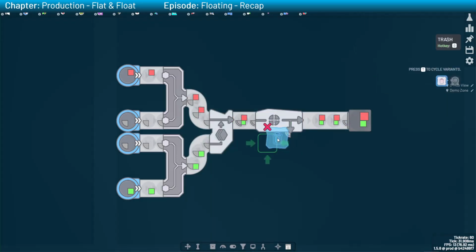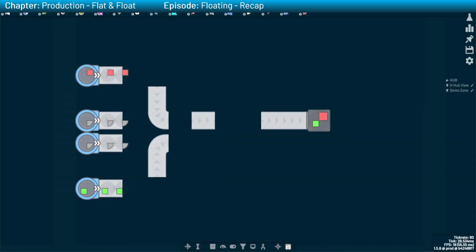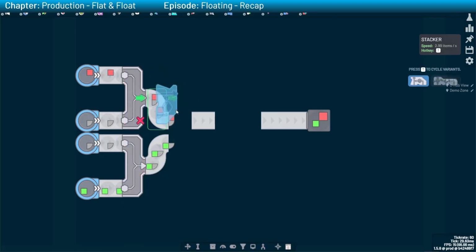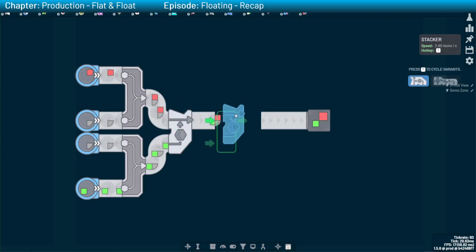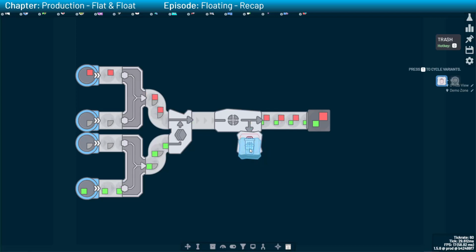And that has implications because it lifts the restriction that you can only create floating pieces that strictly occupy 2 adjacent corners. With the laser cutter, it is possible to create floating pieces with diagonally opposing quadrants too. You just need to make sure, as before, that your scaffolding bits are in a vacant, empty corner, and then you can cut away the scaffolding and keep the floating piece.